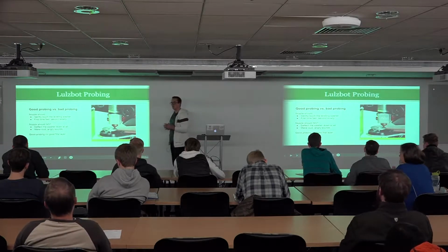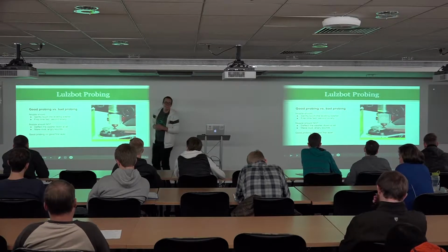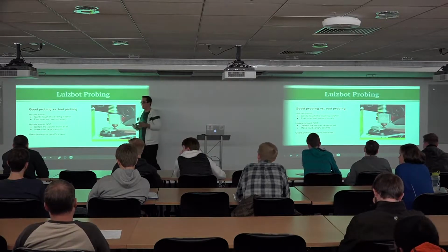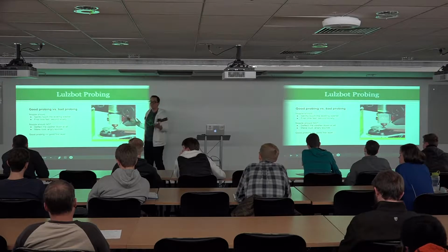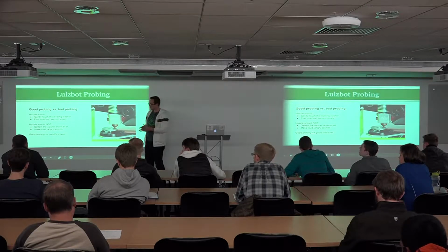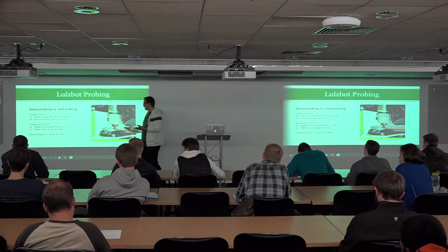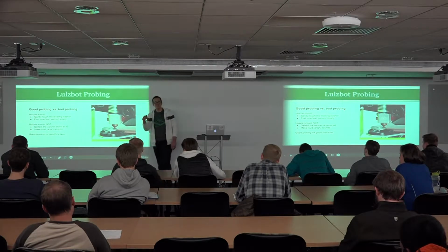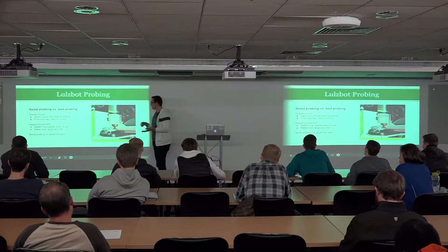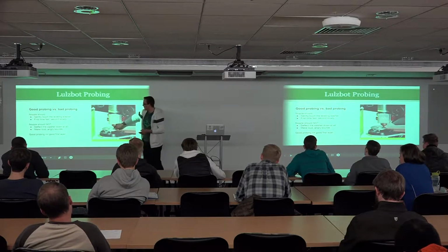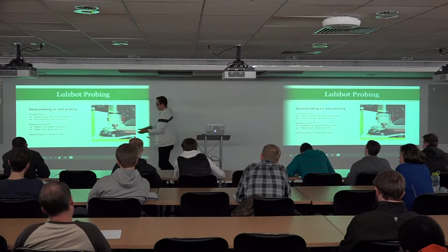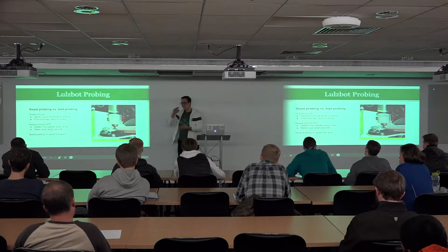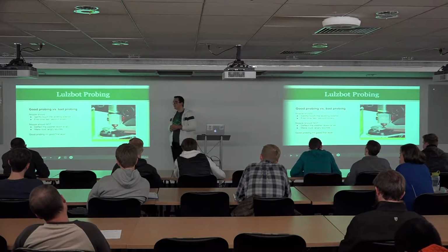Anyone? Hopefully you're not asleep by now. It's an insulator. Exactly. That's exactly what it is. Yeah, so this nozzle, though it's metal, spits out plastic, which is an insulator. So if there's any plastic left on it and they get dirty over time, it won't make a good connection here. Now, it goes through a wiping process beforehand, and that's usually pretty reliable, but not always.